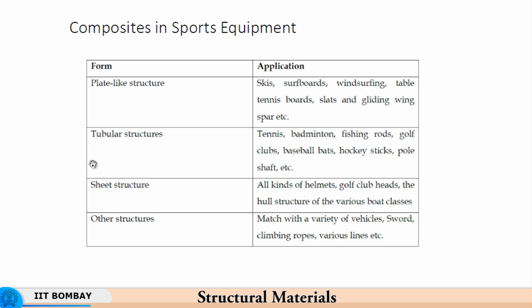For example, the structural component of the lift, which actually withstands the load of the lift and makes the lift move up and down, is a rope. It's a rope of steel. So a steel wire is made into a rope, similar to our coir ropes, and that steel rope is able to take the very high load of the cage of the lift as well as the passengers inside. So typically you have 8 persons or 10 persons, and you have about 600-800 kilos of load as payload taken up by the lift.